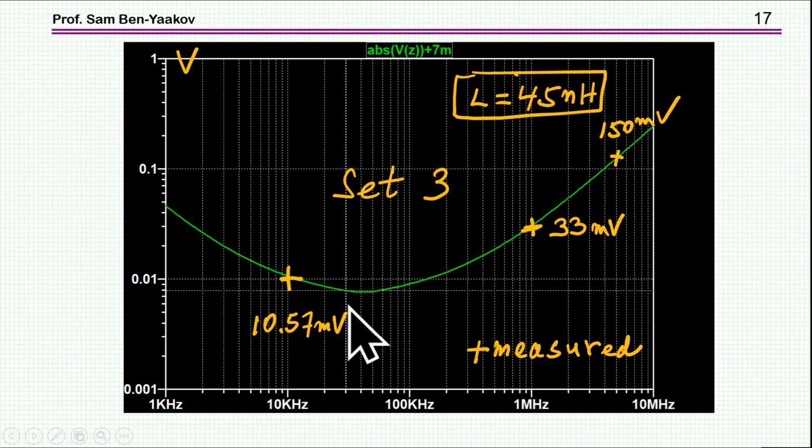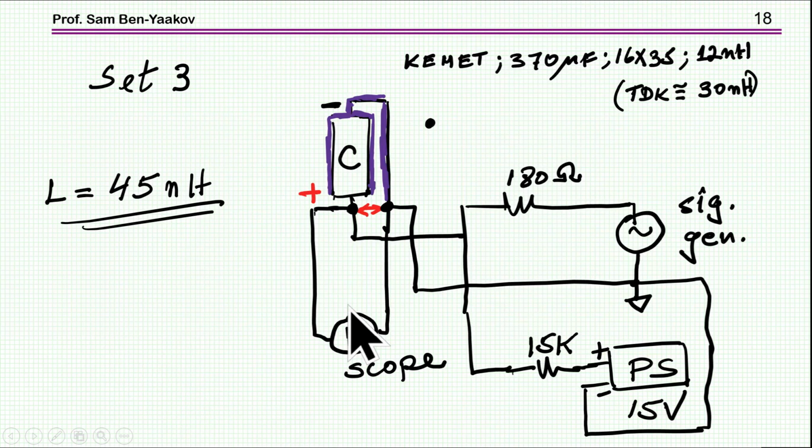So why is there a difference? Well, the difference is because the minus is connected to the casing. So ideally, without having to worry about potential drops or voltage differences on the casing itself, the potential here and here is the same, and therefore the contribution of this area to the inductance is very small because there's no current loop here.